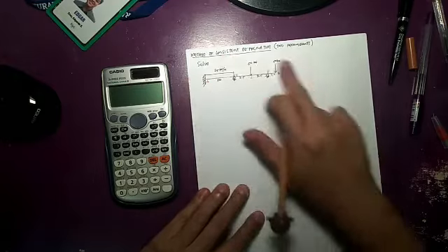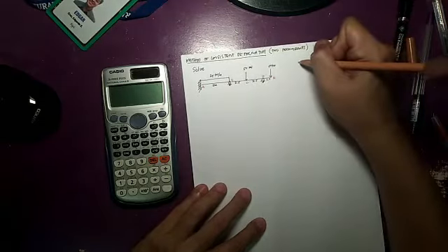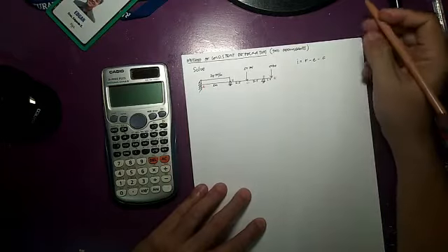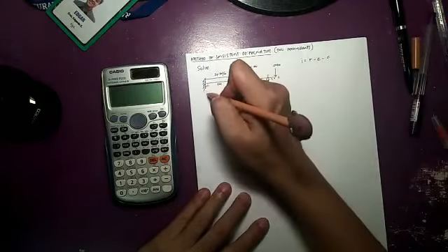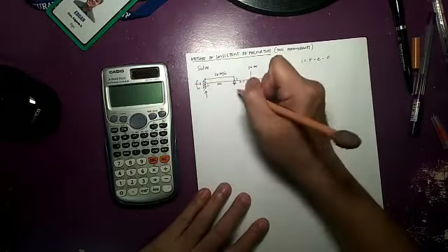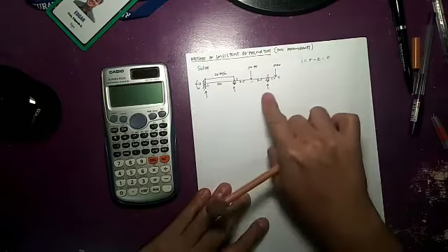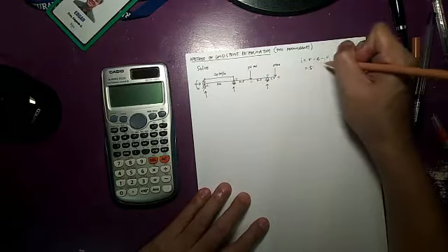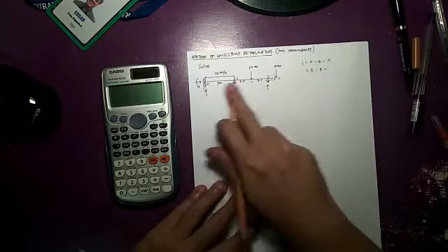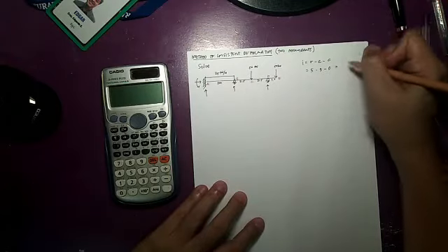So let's say we have this given beam. First we have to check the degree of indeterminacy. I is equal to reactions minus equations minus conditions. For this beam, we have a fixed support here, so three reactions at the fixed support, one at the roller, and another at the roller. So 3 plus 1 plus 1, a total of 5 reactions, minus 3 equations of equilibrium. Then we don't have any internal hinge on the beam, so conditions are 0. Therefore 5 minus 3 is 2.